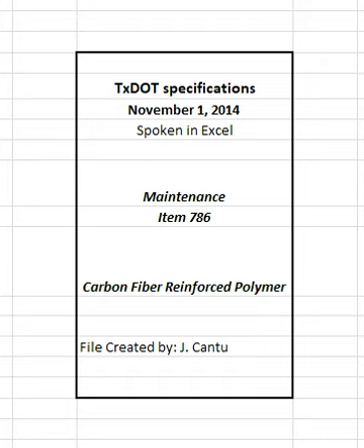Prepare concrete substrate surfaces to promote continuous intimate contact between the CFRP and the concrete by providing a clean, smooth, and flat or convex surface. Grind away all irregularities, unevenness, and sharp protrusions to provide less than 1/32 inches surface profile deviation.